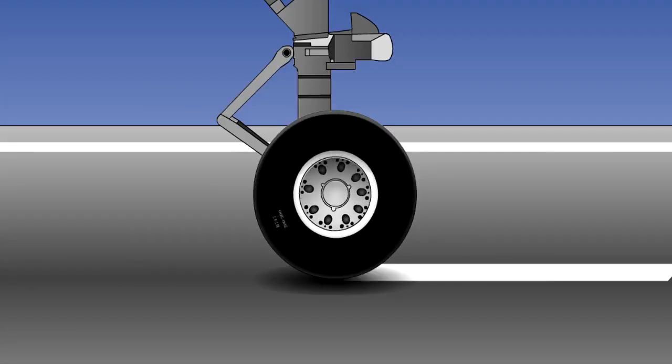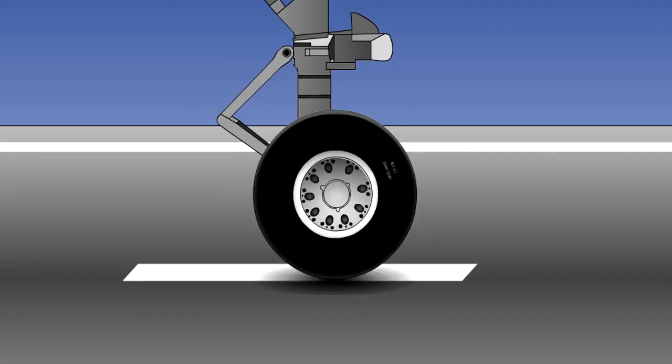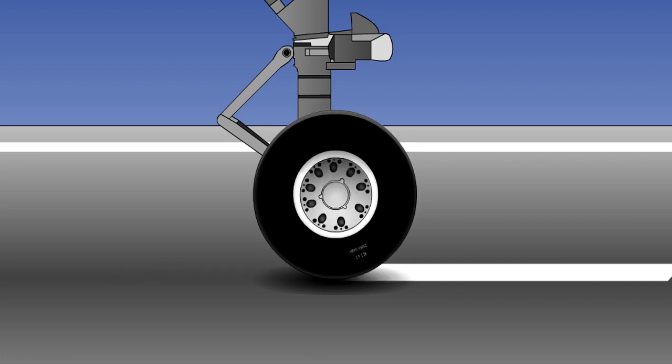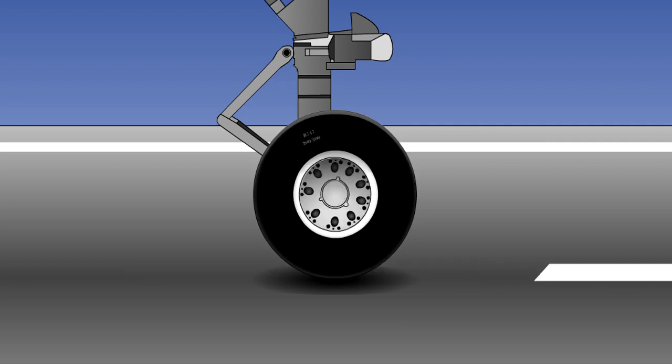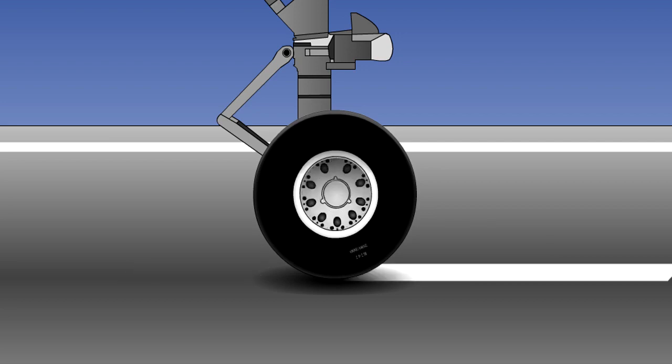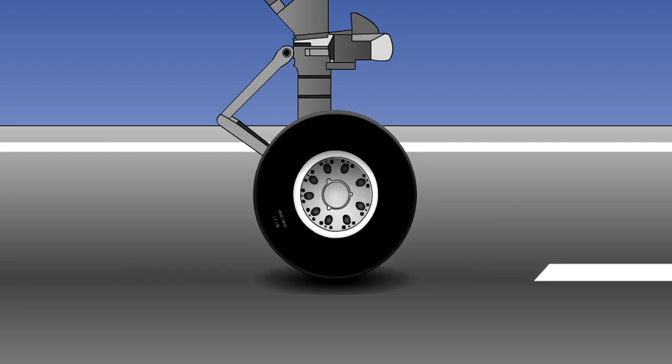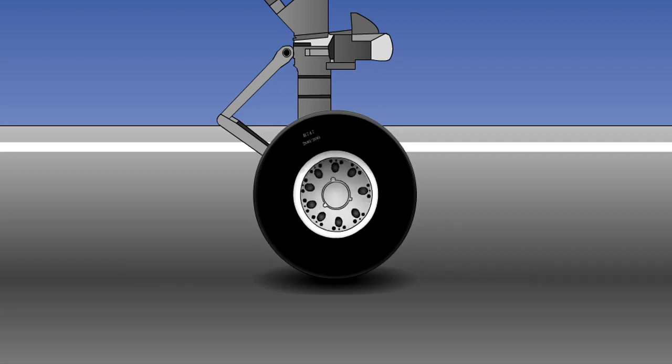When in service, particularly during heavy braking, there is a tendency for the tyre to rotate or creep around the wheel. This creep, if excessive, will tear out the inflation valve on a wheel fitted with an inner tube, causing the tyre to burst. Creep is less likely to occur if the tyre gas pressure is correctly maintained. The procedures for doing this are explained in the aircraft tyres lesson, but additional features to prevent creep may be incorporated in the design of the wheel, and we'll look at two such features now.